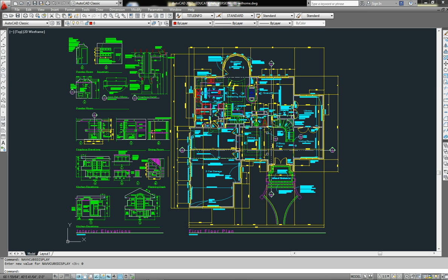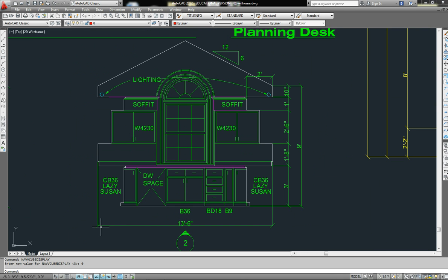The way AutoCAD stores its images and files is through coordinate systems. If I zoom in on an object down here, notice as I hover over the different points with my cursor here, the coordinates on the bottom on the status bar here change. So what happens is that every line, instead of being stored as a bunch of pixels, the line is simply stored as two coordinates, the coordinates of the start point and the end point.